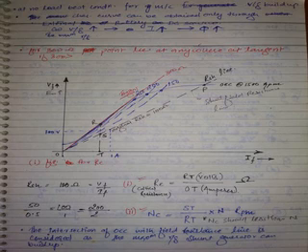Even though you can't recognize it, let us say this OCC is for 1500 RPM, and let this OCC be for 1200. Where is point P now? Where is point P? This one, right? So what happened to the maximum value of the machine? Decreased. As the speed decreases, automatically it has decreased.